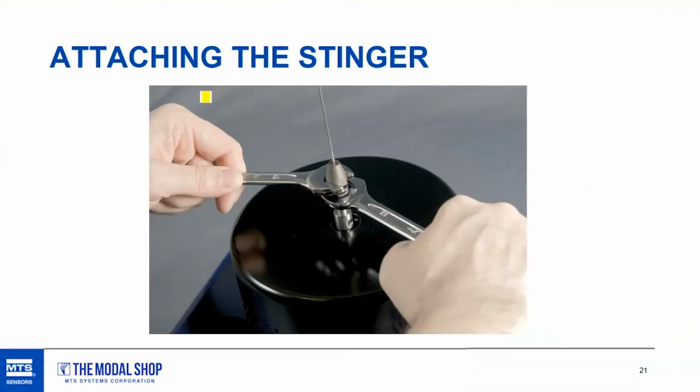And one other aspect when you're compressing that collet, you always want to make sure you're using a counter wrench. So you have one wrench that's holding, and you're not applying any torque into the flexures and the armature that I mentioned before. You're just compressing the collet to hold the stinger in its place.